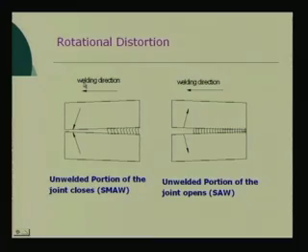The plate edges were aligned to have a uniform 5 millimeter gap, and you started from one end progressing to the other. Halfway through you will find that at the other end it is closing, and truly if you continue, the plates will simply overlap, as if the plates are rotating.